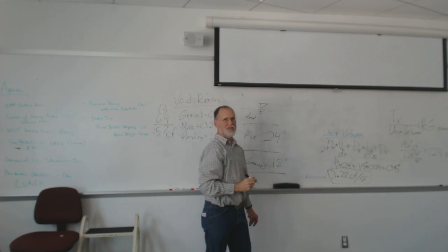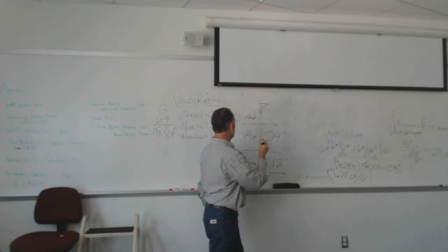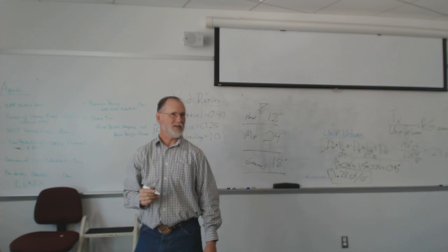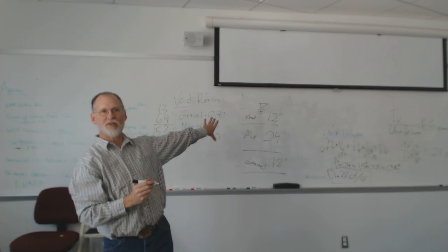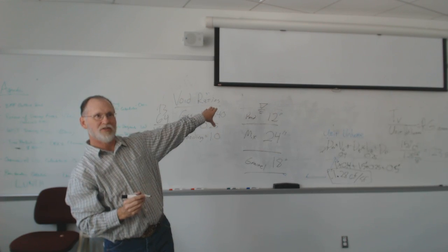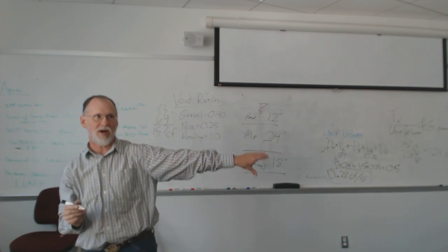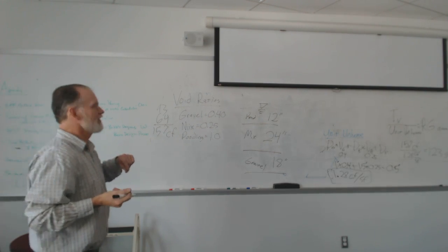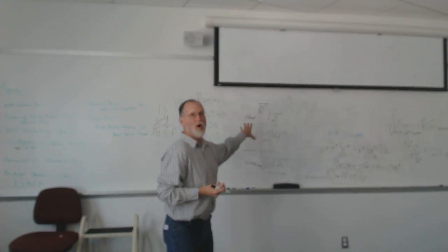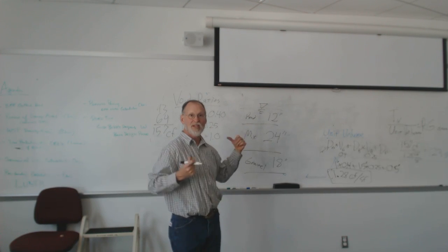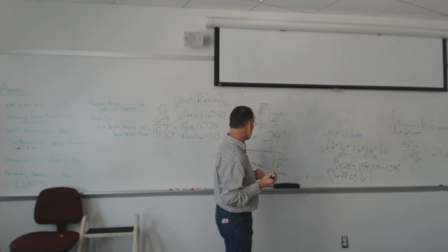24 inches of biomix and 12 inches of ponding. Just looking at these numbers, how do these compare to the ones we just had? All bigger. So what's going to happen to our footprint of our required rain garden? It's going to shrinky dink it, right? Does that make sense? We can hold more water in our unit square footage, so we're not going to need as much square footage. Let's see what those numbers are.